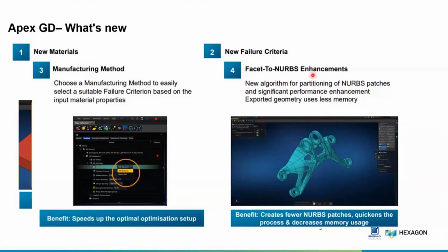Then comes the NURBS geometry. This might be quite interesting. If you have any CAD file that you want to convert into another format, it can be done with the NURBS option. Or even if you have a solid file or STL file which is non-editable, you can bring in the STL file and convert it into a STEP file or Parasolid or XT, whatever format you want. It can be converted into an editable file format using the NURBS option.